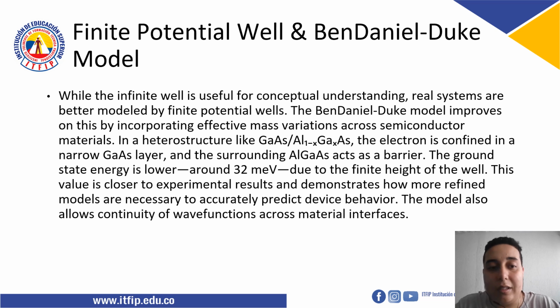The electron is confined in the narrow gallium arsenide layer and the surrounding aluminum gallium arsenide acts as a barrier. The ground energy is lower, around 32 millielectronvolts.